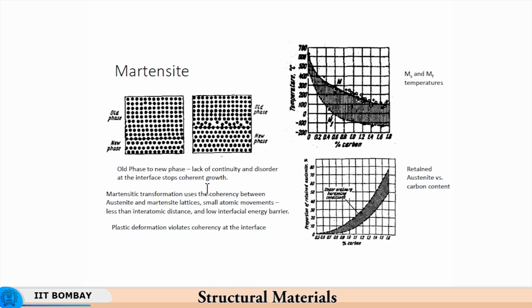Sometimes martensite start is at room temperature or slightly higher than the room temperature, martensite finishes below the room temperature, and as the material continues to experience strain, the martensitic transformation moves towards completion, because martensite finish moves upwards to higher temperatures.